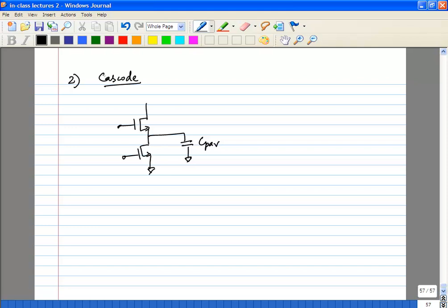And the other thing, what would you do with the gate of the cascode? Typically you would connect it to VDD in most of these cases. That's not a problem. You want to get maximum headroom for the main amplifier. Okay, so finally,